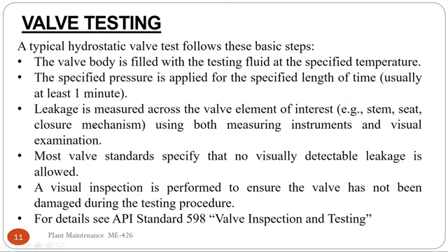Now after 1 minute, check the leakage across the different elements, leakage across the valve, and do a visual inspection as well. If there is no leakage, it is okay. Most valves specify that no visually detectable leakage is allowed. A visual inspection is performed to ensure the valve has not been damaged during the testing process.